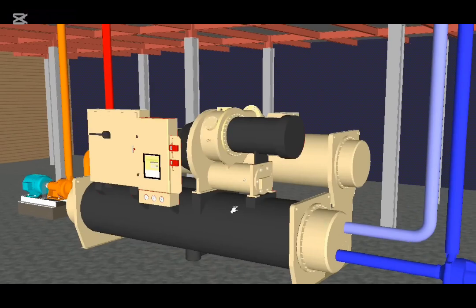Inside the chiller is a separate system which is running around between the compressor, the condenser and the evaporator, as well as the vane guide at the bottom there. And that is a refrigeration cycle happening in there. What's happening there is the heat within this pipe here is being carried away by the refrigerant and sent into the condenser, where it can dump its heat and be taken away to the cooling towers.